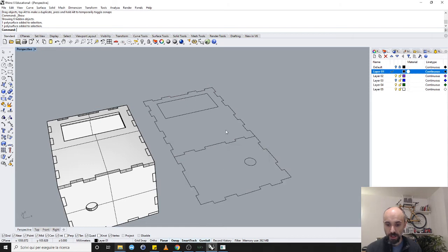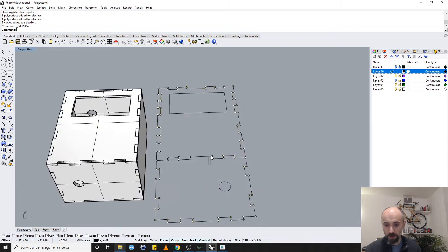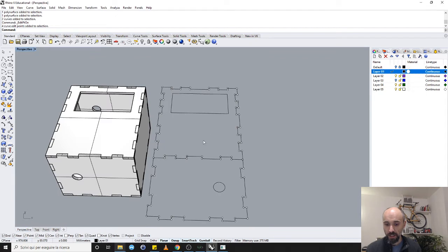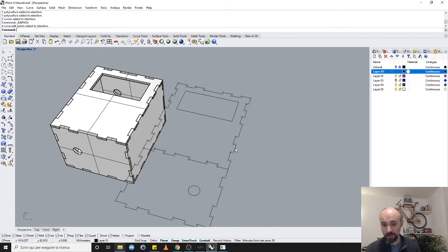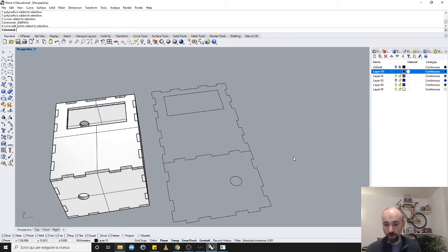So let's take the two lines here. It's enough to modify both lines by a certain amount, let's say 10 millimeters, something like this. Now, this line is not symmetrical anymore, and this piece is not symmetrical anymore, but in the wrong way. So I have to modify this line as well to be sure that this cannot be rotated 180 degrees. So this is just to prove that you have to pay attention when you work with parts to help people to assemble the parts as well.